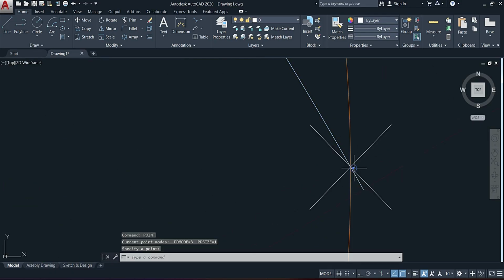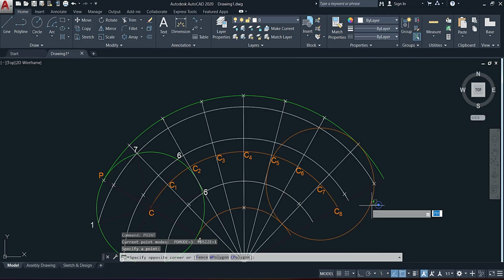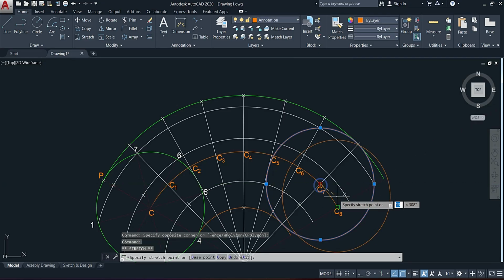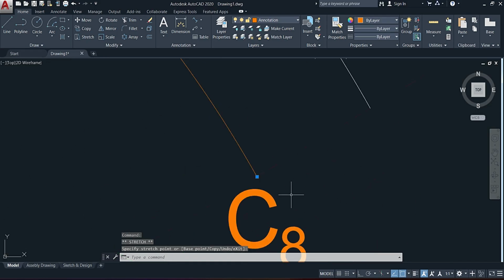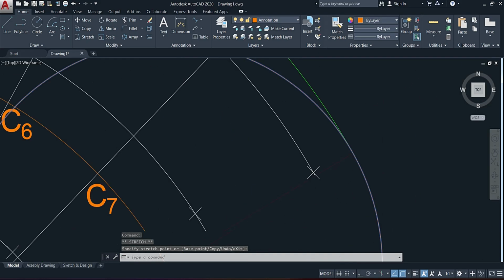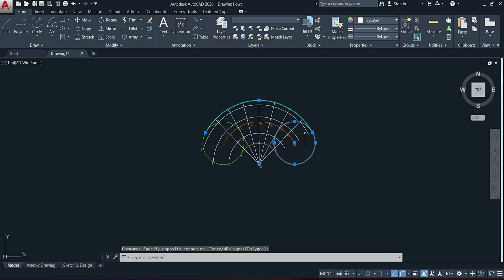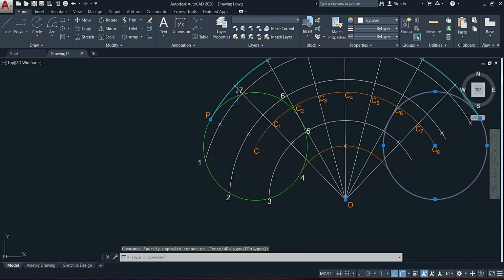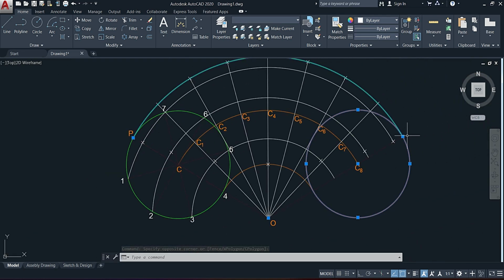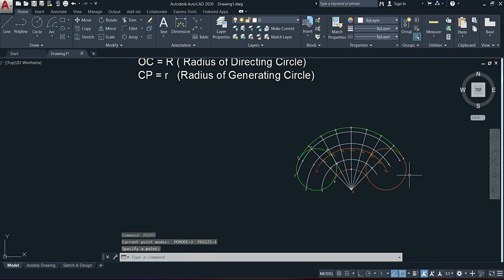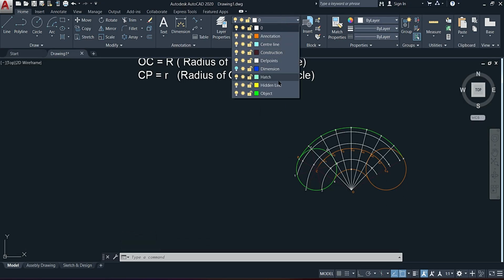Alright. And then finally, let's make our way to C8. Alright, my C8, and where does it intersect? By default, right here, because this is our C8 line. C8, which is point P, that's where things end. So let's add a point there to close things off. Alright, now from that, you can now draw the locus of your point.